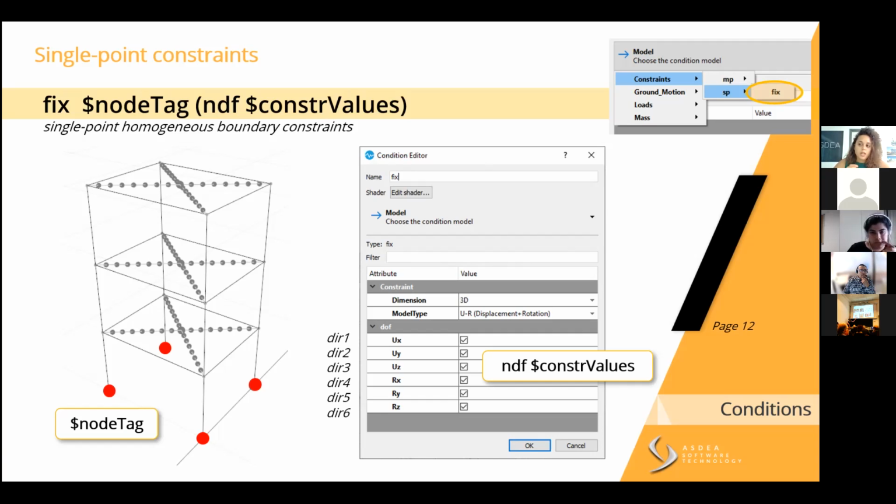So for example, the surface load had a specific drop-down menu where you could define if the direction in which you were applying it was local or global, but normally it's all global. So here, I don't have my reference system, but X, Y, and Z are the conventional X, Y, and Z, and the same for the rotation. I added these names here because sometimes, for example, in a zero length element, degrees of freedom are called like this. They're not called like we call them in STKO.